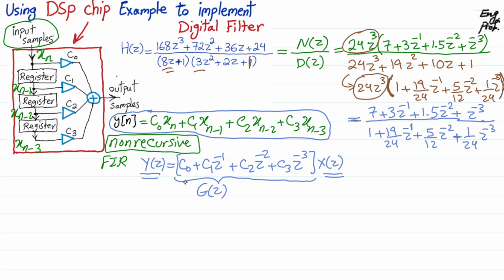And as you can see, C0, C1, C2, C3 are programmable multipliers, so we can program whatever we want. But as you can see, as I said earlier, this filter can only realize a third order FIR. So very nice. We are also in need of third order implementation for the polynomial in numerator and polynomial in denominator. But the thing is, polynomial in numerator is only FIR, not in the denominator. So what is the thing we are supposed to do then?